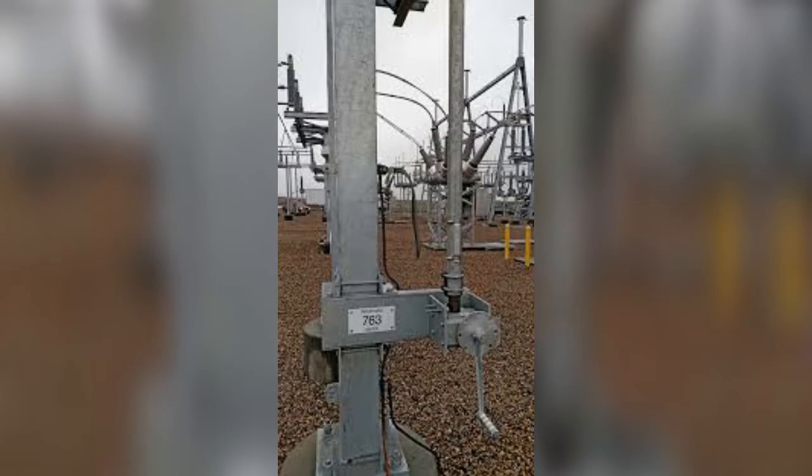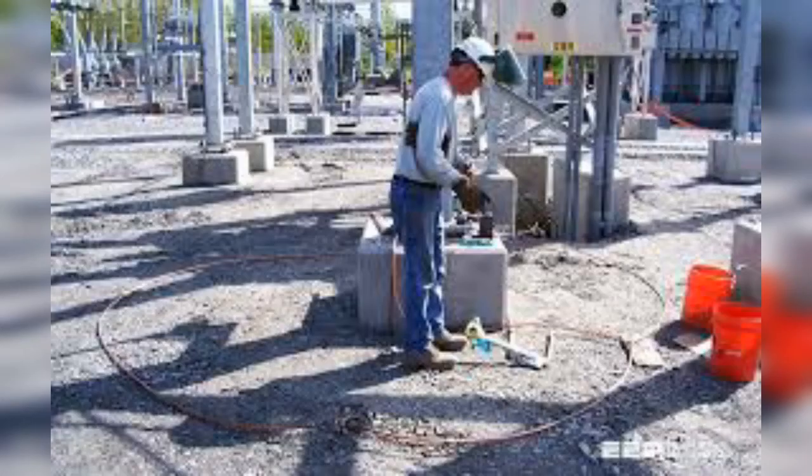Safe grounding requires the interconnection of two grounding systems. Here we are discussing the two main types of grounding. The internal grounding of a switch or a substation consists of a grounding system buried at some depth below the earth's surface. Internal grounding is one type of grounding, and the second type is accidental grounding, temporarily established by a person exposed to the potential gradient in the vicinity of a grounding facility.